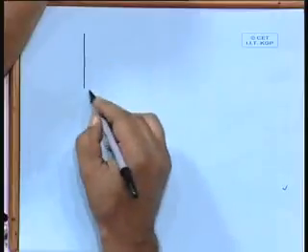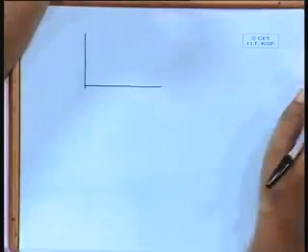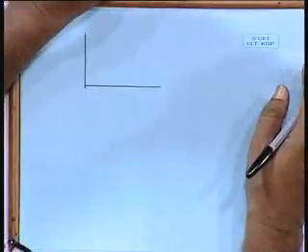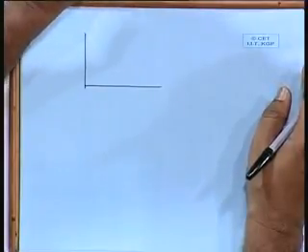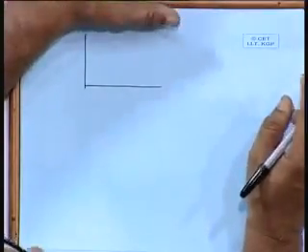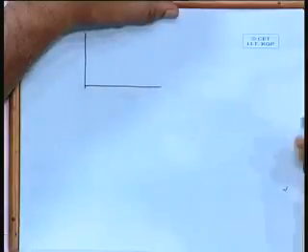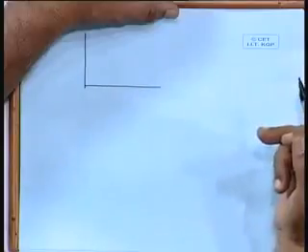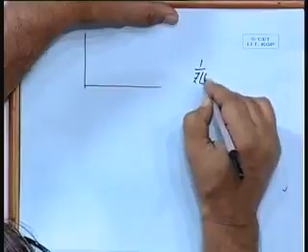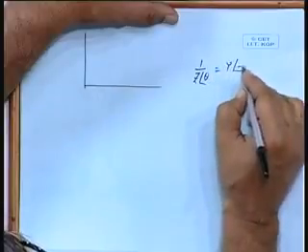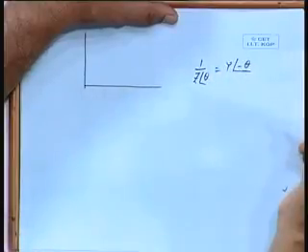Now, so far we have not taken care of the angle part, all right. In electrical engineering, we deal with phasors or impedances with angles. So, when we write V by Z or 1 by Z, the angle associated with Y will be just negative of the angle associated with Z. 1 by Z theta will come out as Y with an angle minus theta.